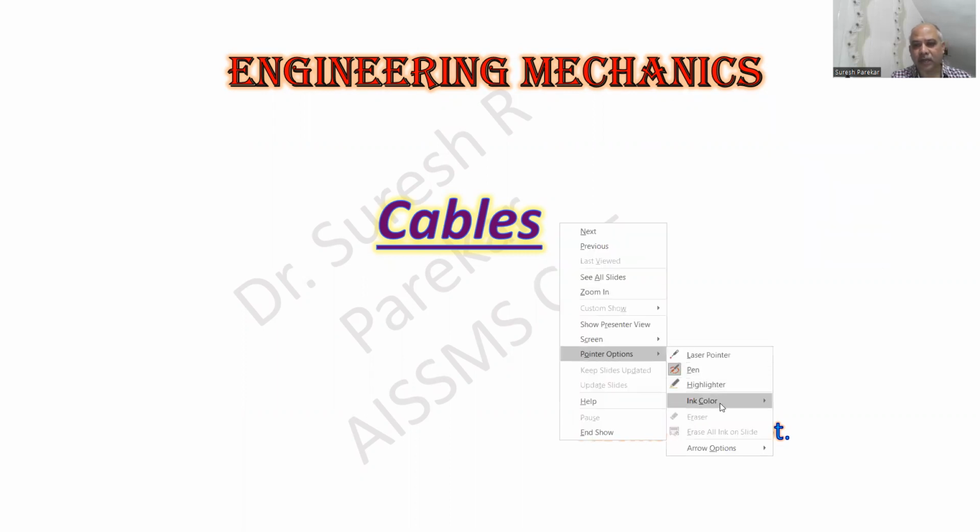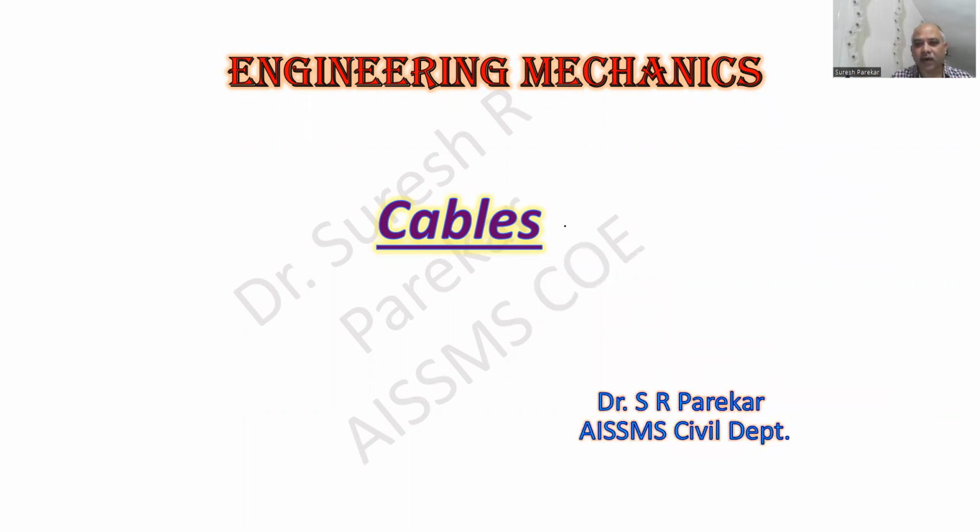In this system of cables, or if we say wires, we always have tension. Cables are not going to resist any compression. So a cable can sustain tension only. That is the most important part we have to keep in mind. Whenever we consider any cable, we have to show tension in it. That means from both ends your arrows should be away, because we know tension means arrows should be away from the joint.